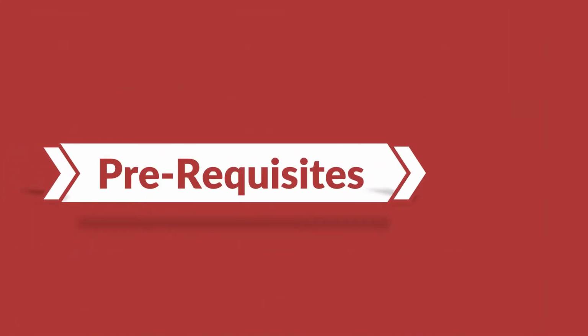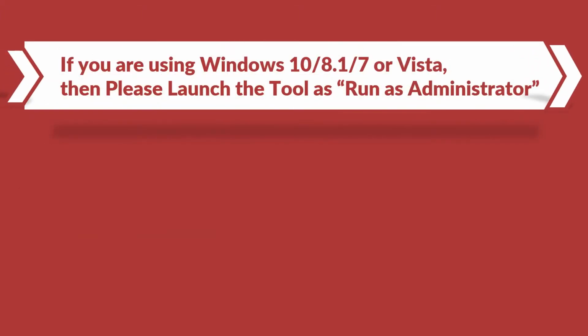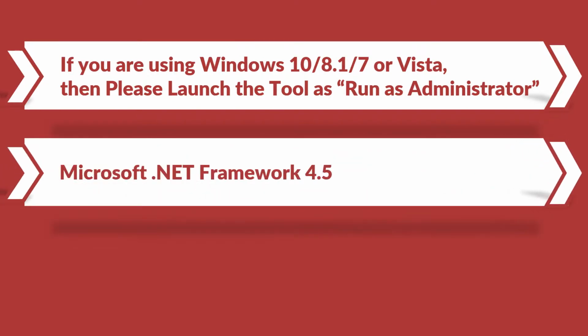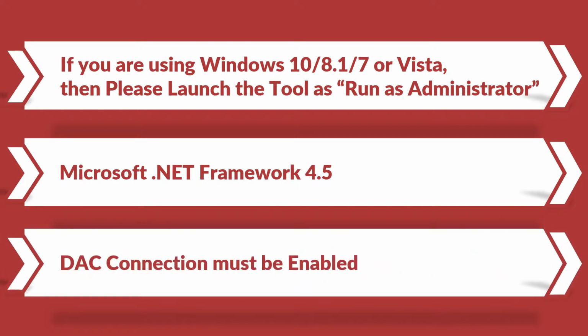Now let's check out the prerequisites before installing the software. If you are using any of the Windows versions mentioned here, then please launch the tool as run as administrator. Make sure that the Microsoft .NET version mentioned here is pre-installed on your system. And also make sure that DAC connection is enabled, either by SQL Server Management Studio, or by tsql command.